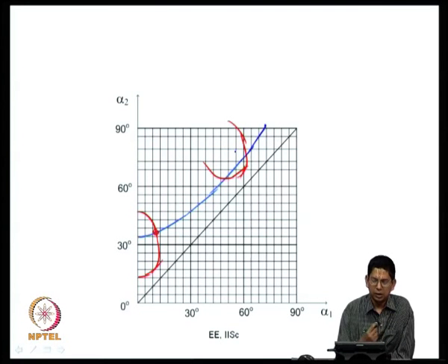Many a times you can start from a point, as I said, that 60 comma 90, there is an equivalent point at which the waveform is a triplen frequency waveform. It can be a third harmonic, or a ninth harmonic, or a 15th harmonic. You can always come up with some switching angles for any number of switching angles, alpha 1, alpha 2, alpha 3 say.